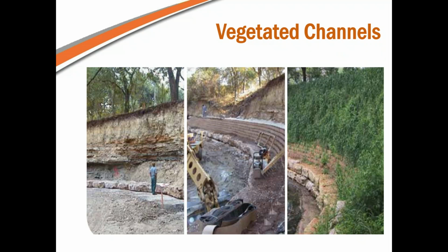Here you can see repair of severe erosion at the bend of a channel. A multi-layered channel system on one side of the channel was built and vegetated. When GEOWEB protection is on both sides of the channel, the horizontal footprint can be built extremely narrow, allowing room for additional stormwater to mitigate flooding potential. This is popular in residential areas where people don't want to give up half of their backyard to stormwater channels.